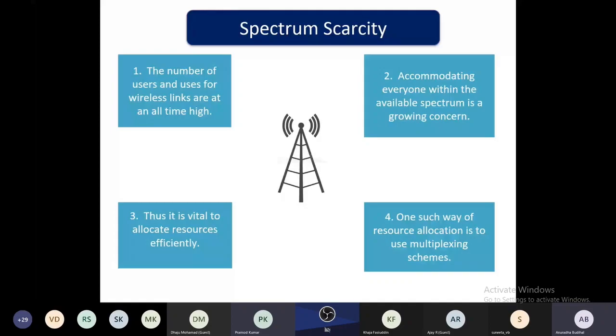Multiple carrier modulation is a technique for transmitting data by sending it over multiple carriers, which are normally closely spaced. It has several advantages, including resilience to interference, narrowband fading, and multipath effects. As a result, multiple carrier modulation techniques are used for data transmission, as they can provide an effective signal waveform which is spectrally efficient and resilient to real world environments. So this is a brief introduction about why multiple carrier modulation is used.